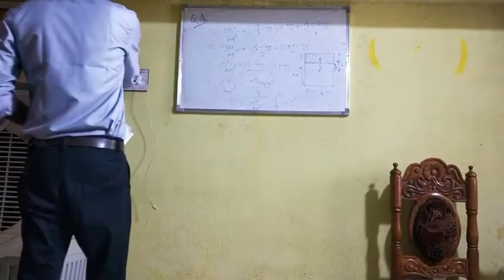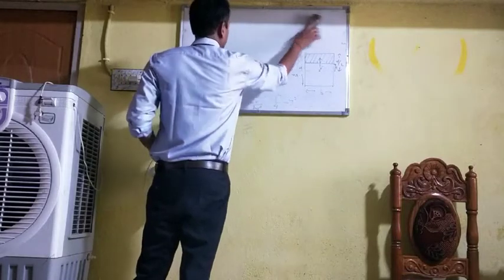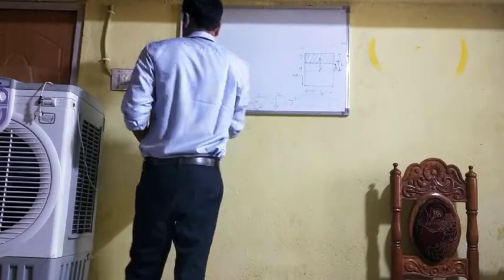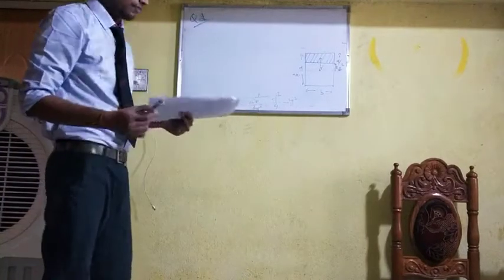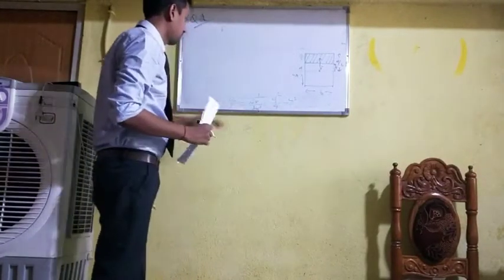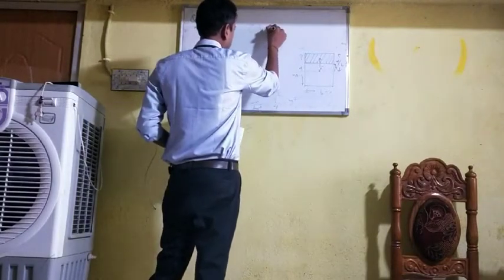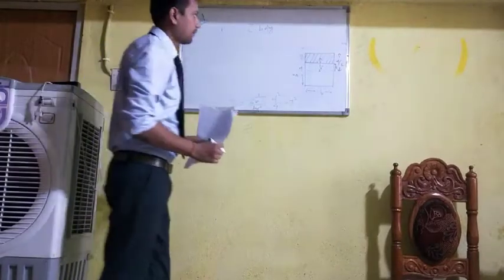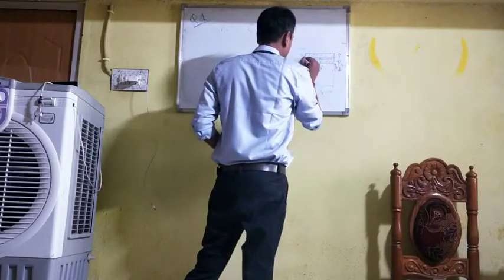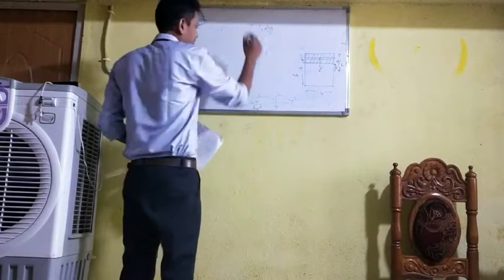So after the shear stress, we have to find out the shear force. So let's find the shear force. What is the shear force? So the formula for the shear force will be tau into area will be B into dy. So we have to take a small section on the hatched portion. That will be this one. And this is dy.